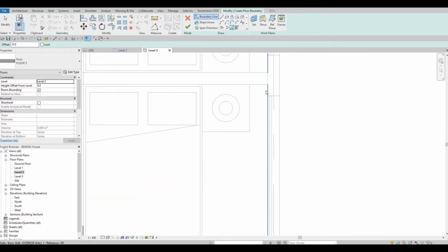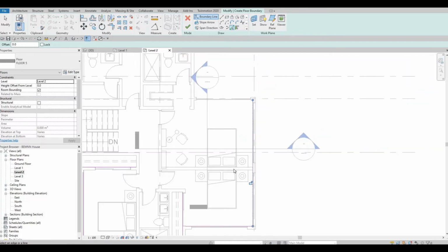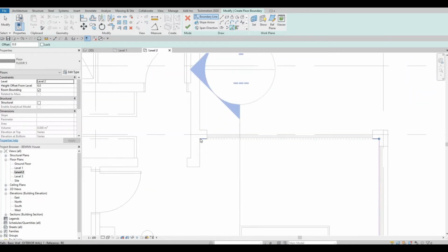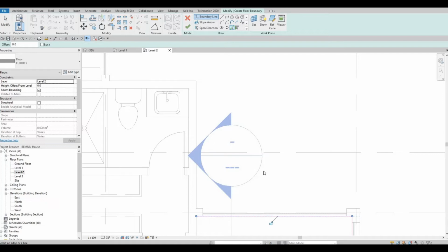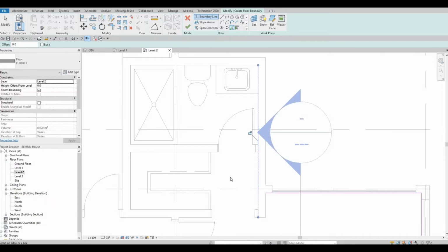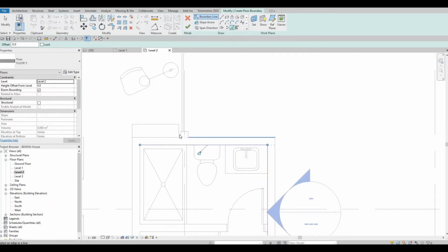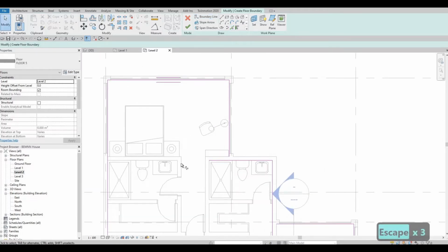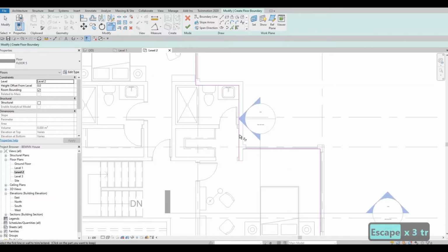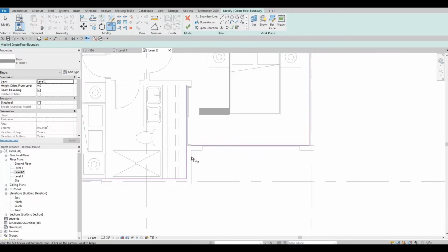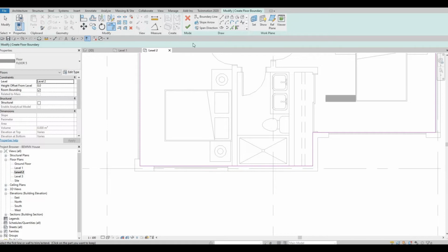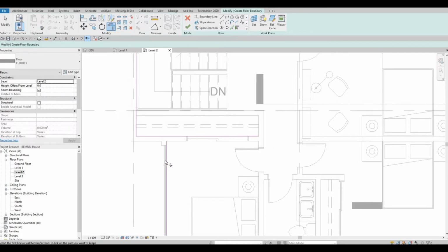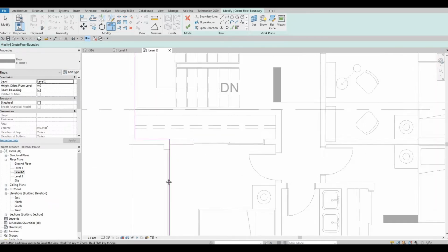We just need to add lines for now, and then we're gonna deal with how we're gonna extend those ones later on. So now we're going to TR, trim and extend first. So for me, it's better sometimes to just finish the trimming first, click on finish, and then do the edits later on.